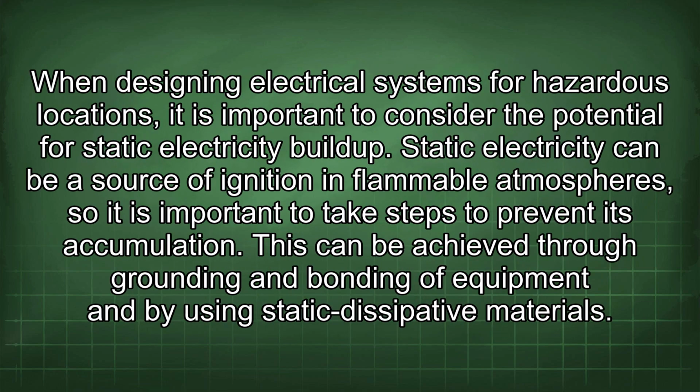When designing electrical systems for hazardous locations, it is important to consider the potential for static electricity buildup. Static electricity can be a source of ignition in flammable atmospheres, so it is important to take steps to prevent its accumulation. This can be achieved through grounding and bonding of equipment and by using static dissipative materials.